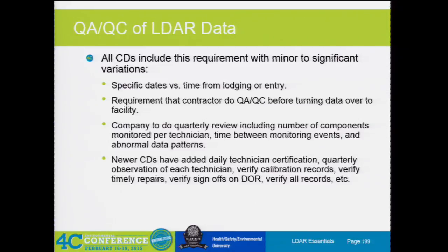Others have gone to a very detailed review of DORs. So DORs is a license to leak. And with that, you want to make sure that you're getting the right people to sign off on it. So by doing QA/QC and making sure, okay, does this valve truly need to go on DOR? Can I do this? Let me go talk to engineering. It's another way that people are making sure that you aren't just putting things on DOR or just putting things temporarily out of service because you don't want to do it that month. You're staying away from those troubles. You're putting in that information so that everything gets better.